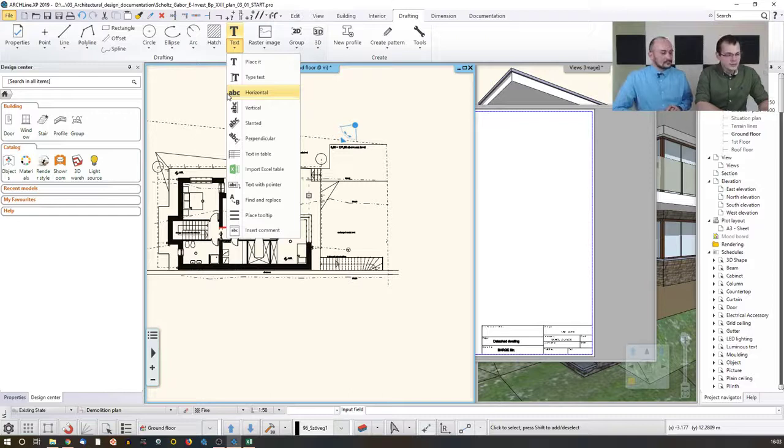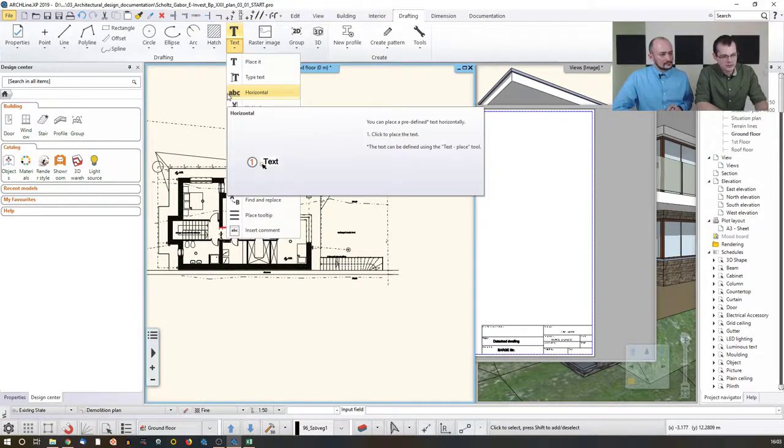Here's another one. When drawing drainage and pipe services on plan, is there any option to set Z values to the lines to show schematics for pipe isometrics if required for building control purposes? Z values are not portrayed automatically by default. So for instance, if you use the sweep command to create a pipe drainage system, then if you want to mark the elevation values on the floor plan or on the layout, you have to do that manually with text, right?